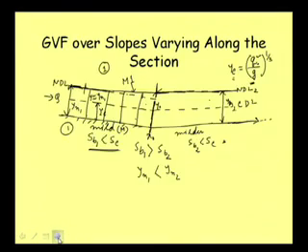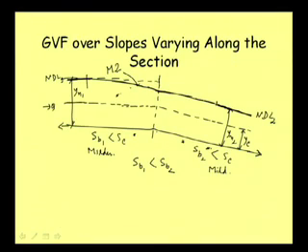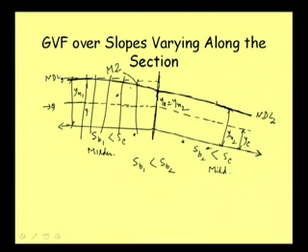Well, let me just talk about computation also. Now, when we think about computing this profile, again we will have to take this as the known section, because from this depth we will be knowing y0, the control section is nothing but yn2, we know that. And from here we start computing, and then we can go up to this point where y is almost equal to yn1.